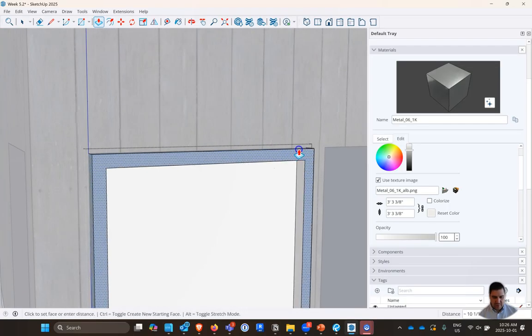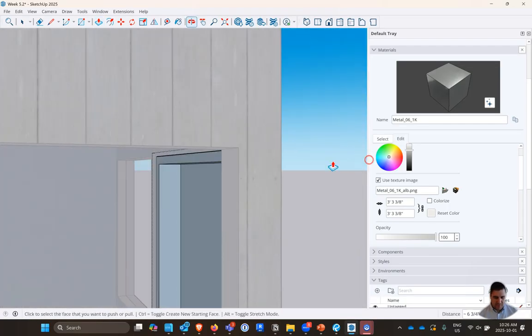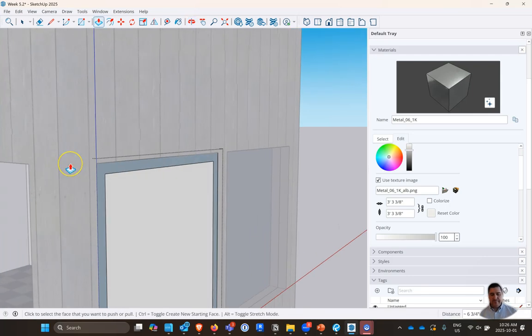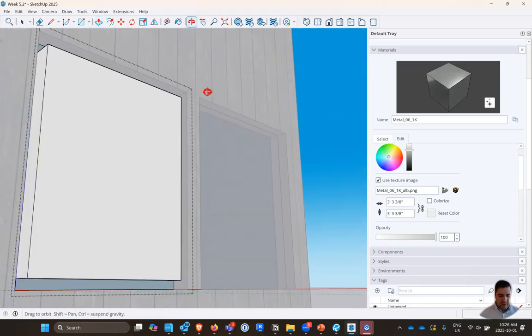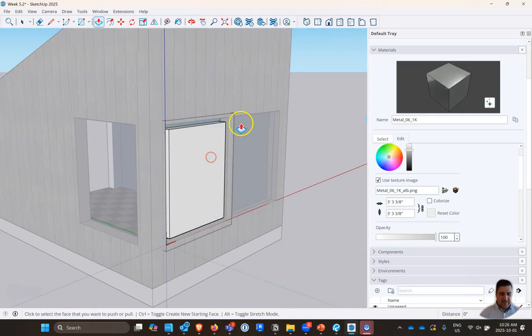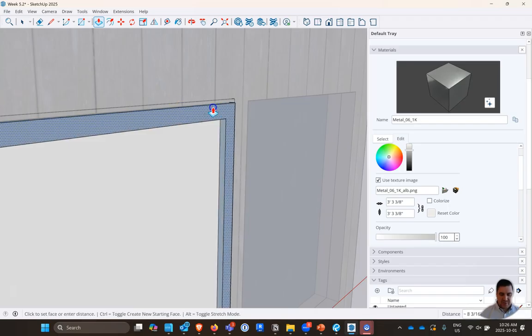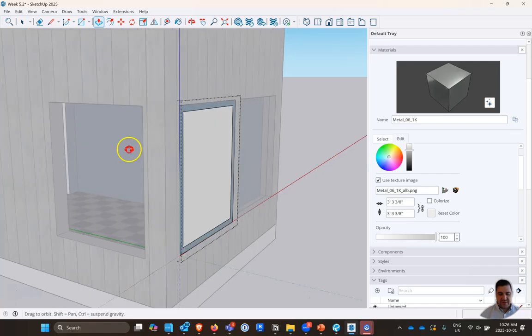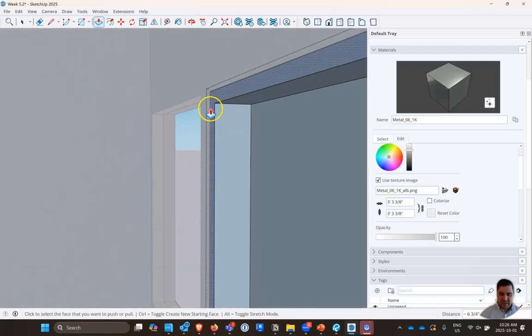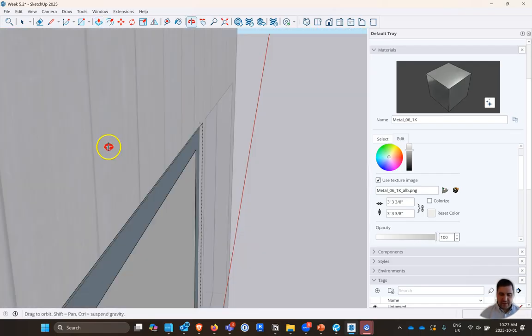do that, which is not necessarily what I want. So I extruded it in. I did that really quickly. And then I extruded it back out. So because when I extruded it in, it created a void like this. I want to keep that solid object, so I'm going to extrude it back out to the edge, and I'm just using my mouse to line up with one of those edge elements. And now it looks like we kind of have a frame sticking in here.